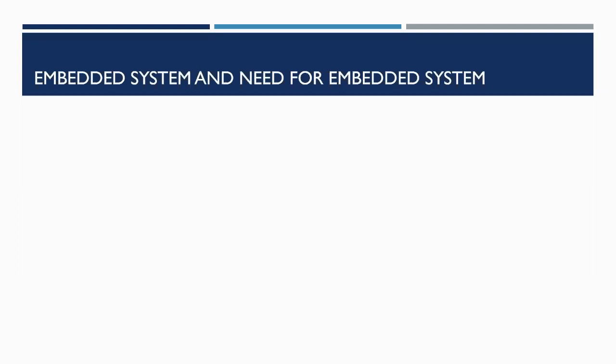Now one can think, instead of doing this manually, if this has to be automated, how will it be? To automate this, there should be engineering behind it, where we need to monitor the tank and monitor the electrical supply. Based on this, if the supply is there, then check the water level of the tank. If the water level of the tank is low, at that time turn on the motor.